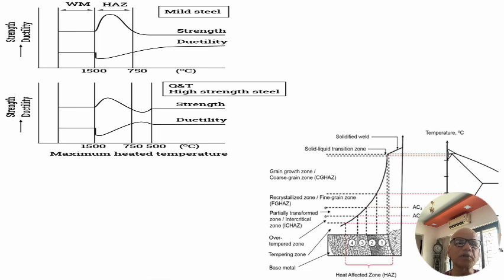So in summary, for this particular topic, I am saying that defects are internal, defects are within the weld, defects are external to the weld, visual defects are there, and NDT detected defects are there, which are hidden inside the weld. There are defects which come because of poor setup, or poor fixturing, or not using a neutral axis, or not balancing the weld, or not using a proper technique like the step back technique. We will land up in distortion, deformation, some mismatch, or shrinkage.